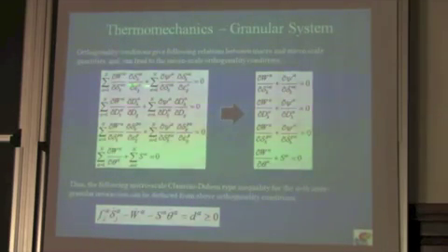All right. The other orthogonality conditions, or what are known as Ziegler's orthogonality conditions, if we introduce those summations in terms of free energy and the dissipation, lead us, under some conditions, to these local orthogonality conditions. So what we're doing here is saying if n is arbitrary, then we can make term by term equality, and those lead us to this set of orthogonality conditions, which implies that there is a similar inequality as at the macro scale at the intergranular level. So we have now obtained a Clausius-Duhem type inequality for the alpha-th intergranular interaction. And this will then help us determine the constitutive equations between two grains.